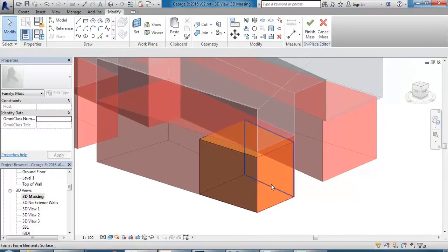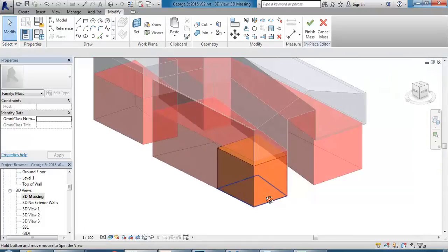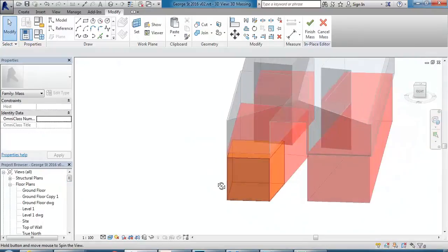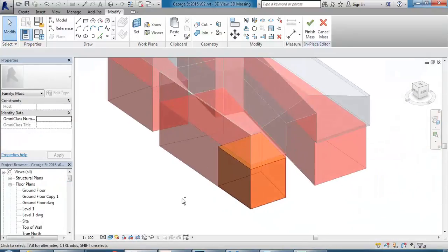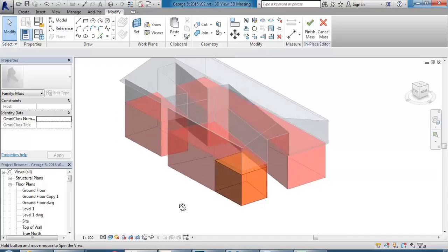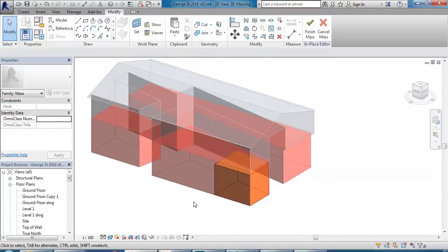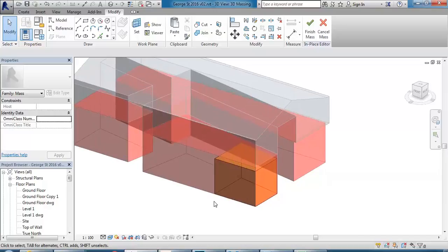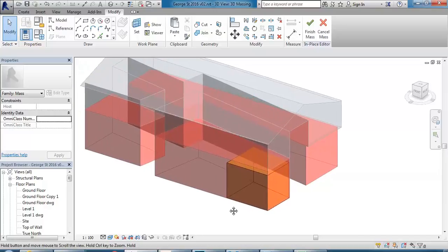Okay, so that's a fairly easy thing you can do, and start breaking those spaces up further. And I just find it's much easier than trying to model in walls and all those other things, where you usually get too much detail. And these block diagrams, I think, are really effective. And you can generate walls and other things from them later if you want to as well. It's not necessary to do that. You can always just draw the walls directly, but sometimes that'll help.